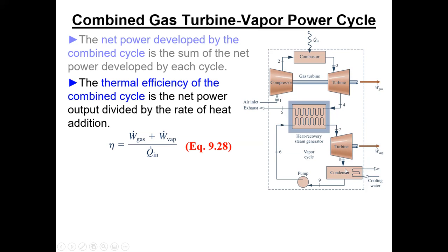they put burners in that hot gas flow so they can put more heat in. So to get maximum steam generation efficiency, they're going to augment the temperature coming out of the gas turbine, because they've done all the calculations, and it's a good investment to burn some more gas to get some more temperature into that HRSG so you can get some more steam out, so you can get more power out.